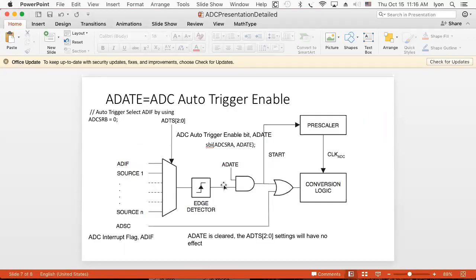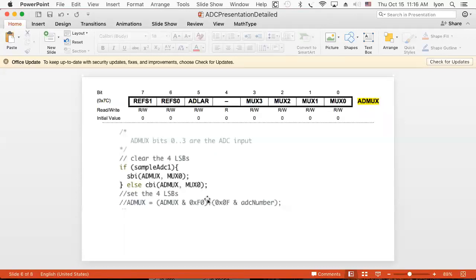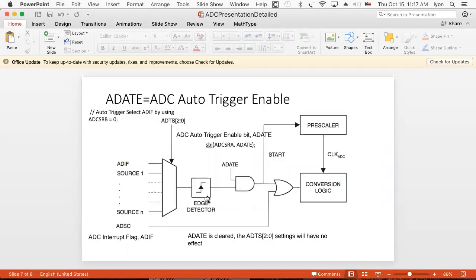So then, and to that point, I should mention to you, when you read the data sheet on this, it says if you have a 20 megahertz clock on your Mega 328P, you have 20 MIPS, 20 million instructions per second. When you have a 16 megahertz clock like we do, you have 16 million instructions per second. So our clock rate directly links to our architecture, which is a single instruction, single data, or SISD type architecture. So if you make this chip faster, it's going to go faster. There's not multi-cores. There's nothing fancy going on. In fact, it's an 8-bit toaster controller.